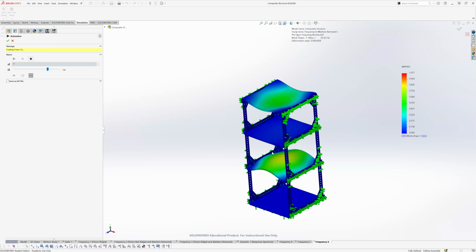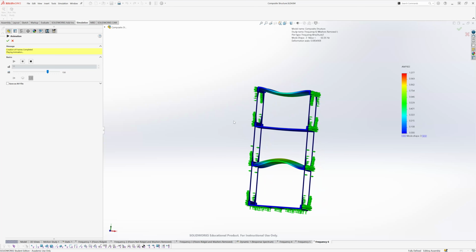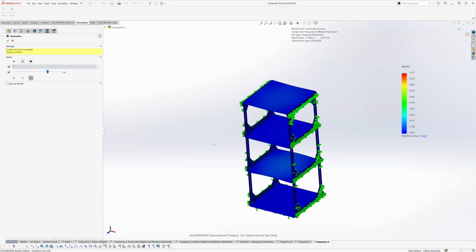This is where frequency analysis is really useful, to see what is happening and whether it's behaving the way you expect, and where some possible areas for further analysis are. Because obviously if it was moving in a way that we wouldn't expect, then that would matter, especially since we want to know what frequencies, or what kind of mode shapes, we're dealing with in our range of frequencies that we're going to be trying to test once we actually build this model.